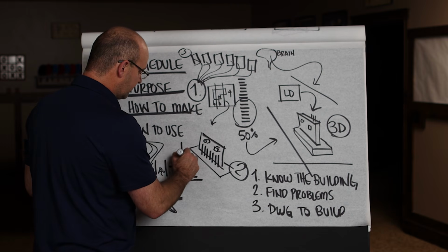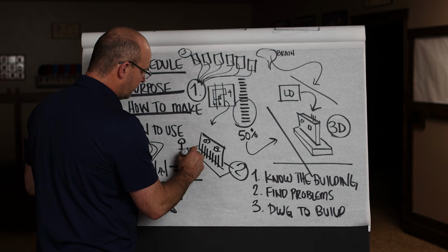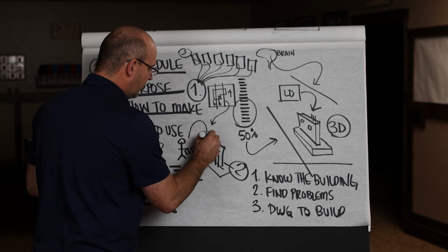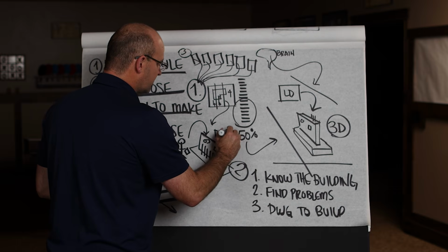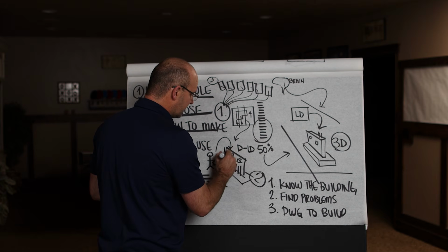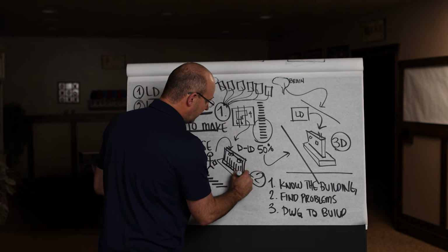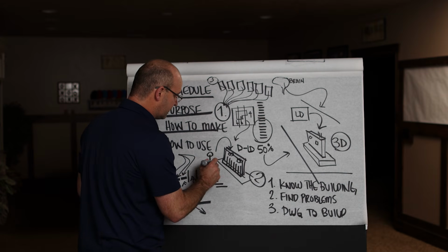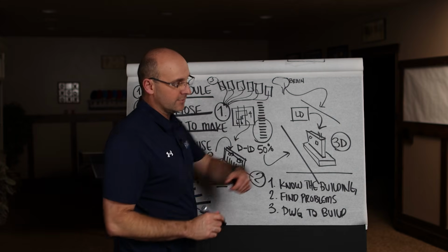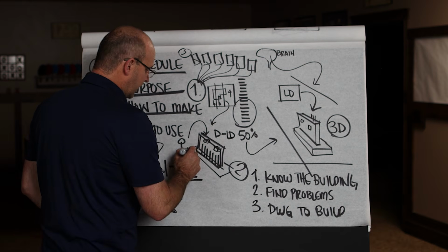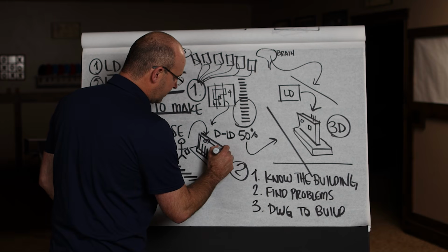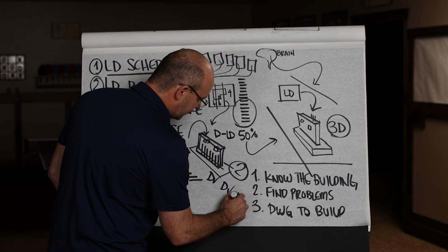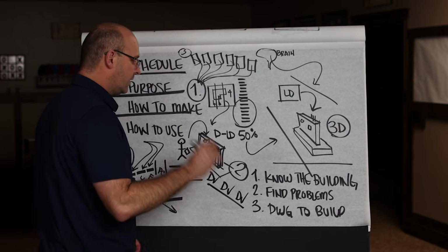You will grab that lift drawing and you'll go out in the field and hopefully build from it, but definitely double check it and make sure that what was built from the drawings gets checked with the lift drawings before you put that second side wall form up, and you place it and you make sure that it's done and locked in and hard and gray. You're going to use that lift drawing to make sure it's right. You can't just give it to somebody and hope for the best. You've got to actually get your butt out there and actually QC that wall and make sure that it's right, and double check, double check the work so that we do not get it wrong.